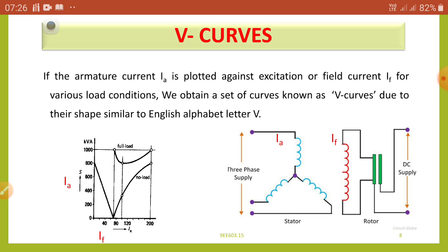The power factor as well as the armature current changes. Now the current starts increasing, and at the same time the power factor moves on the leading scale, and goes on increasing up to the rated field current of the rotor circuit. Note down all readings. Then come to the normal position and switch off the main supply.